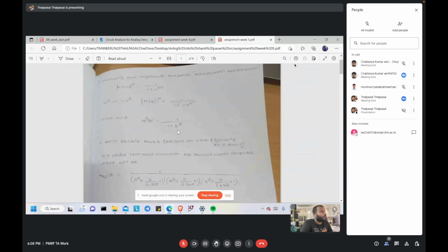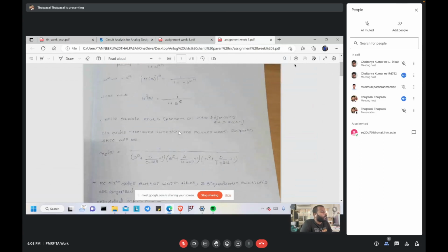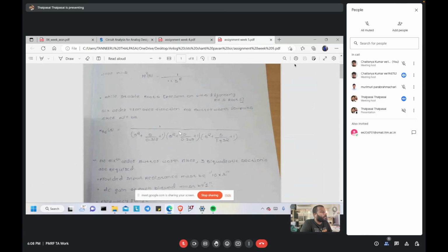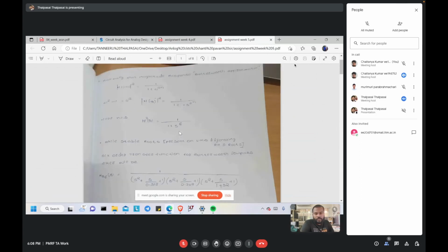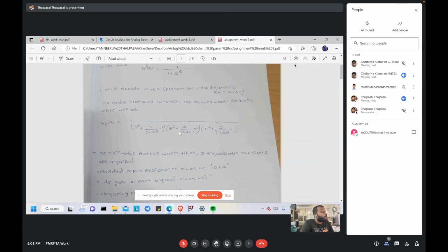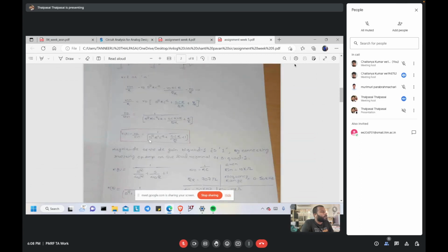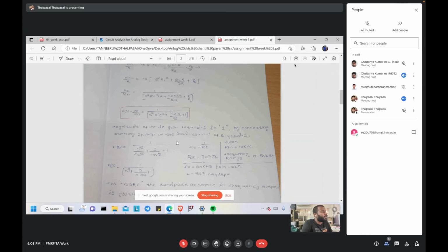Yeah. Basically, you try to approximate the magnitude response. From that, you get a polynomial in s. Basically, you will get three cascaded second order sections, and you will get Q. So Q will be 1 upon 2 cos of 2 pi by whatever order you need, right? Yes, sir. So from there you get this. So yeah, this is basically one of the sections.